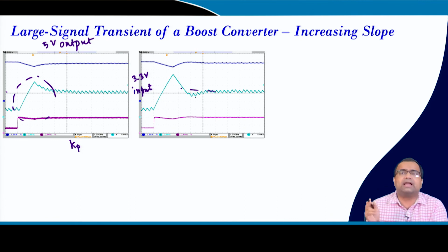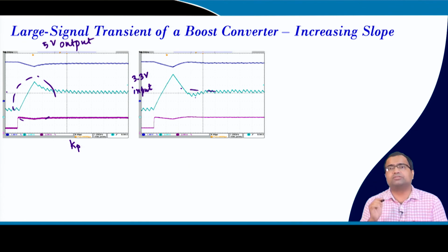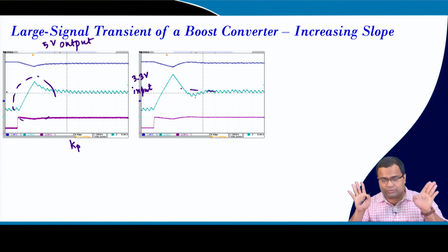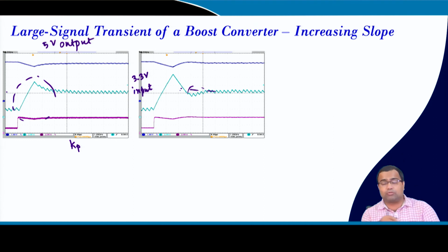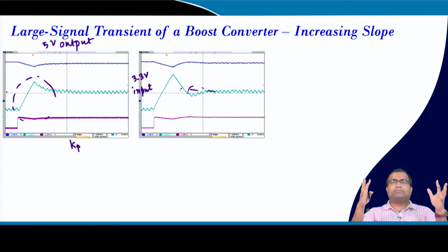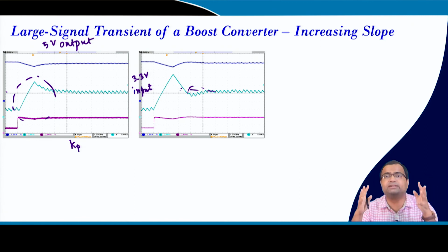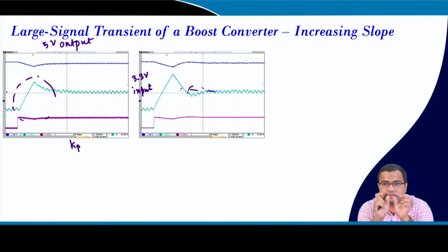But if we increase Kp to a proper value, it is more or less optimal because you see there is a slight overshoot and undershoot in the current. This mismatch is coming because we have a PWM modulator, where the PWM modulator itself has a constant. So, we cannot achieve perfect time optimal, we will get rather approximate time optimal, because the modulator will put a constant in the on-off time, right.